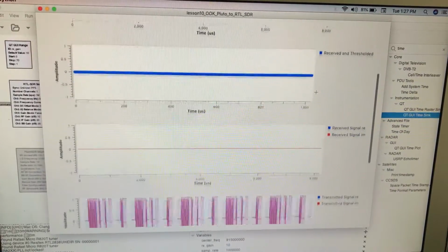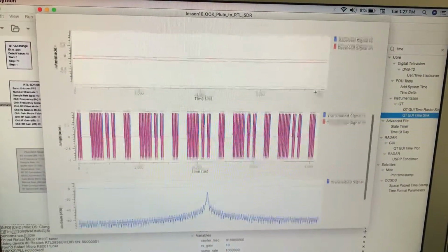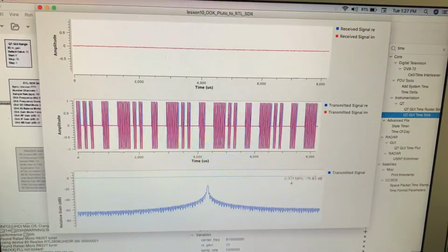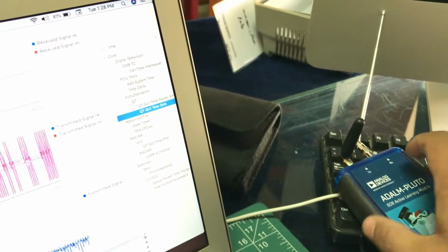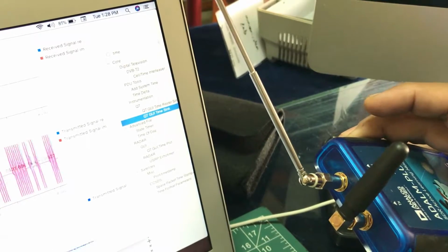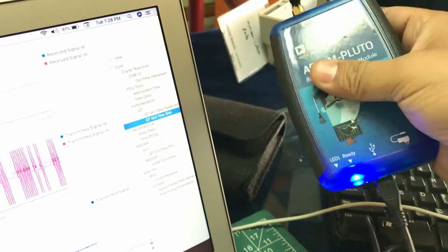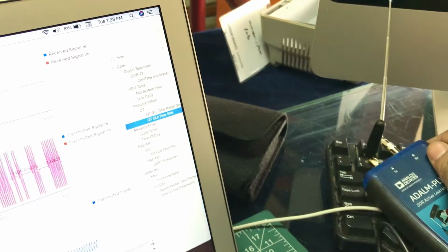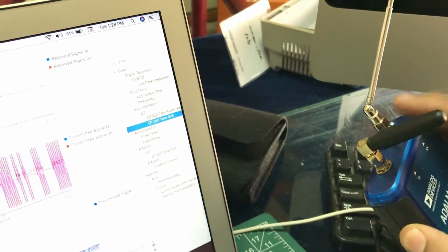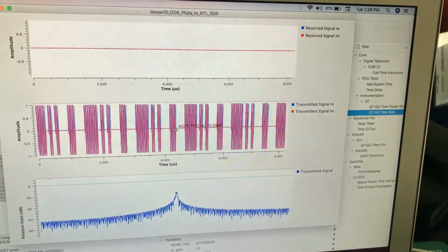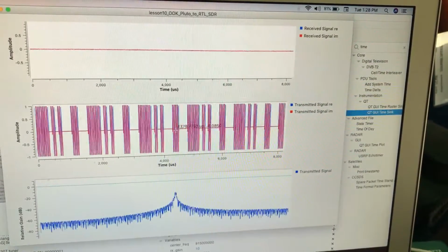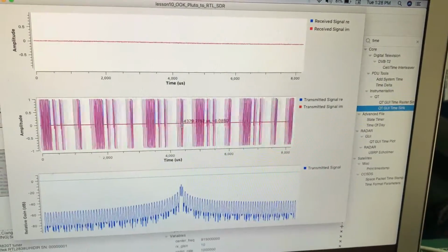This is that threshold. So basically what I'm doing, the graph that you might be interested in is 1, 2, 3 of these guys. Alright, so right now you're not seeing anything. This is what is being transmitted from my PlutoSDR. This is my transmitter, which is transmitting that signal. Alright, as you can see, the lights are on. So this is what is being transmitted from this antenna. This is just another antenna at the receiving side. If you look at this, this is the same bit pattern which I have given, and it is being repeated again and again over 20 kilohertz of frequency.